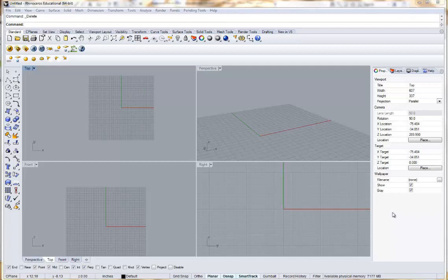Alright, so in this tutorial we're going to cover two things. One is the use of SAT files, basically extending something from Rhino into Revit and plugging ready-made wall systems and roof systems into that construct. There are a couple of different ways that we're going to do that, and I'll show you that in a second. Then we're also going to cover the generation of custom roof planes afterwards.